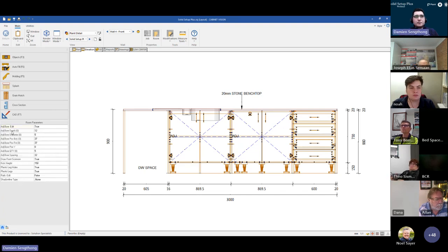By turning it on, you do have the ability to change the depth, diameters, the front and back positions, as well as a Y adjustment if required. So you can move the shelf holes up and down if necessary. Hole or bore quantities, and most importantly, the spacing between each hole.